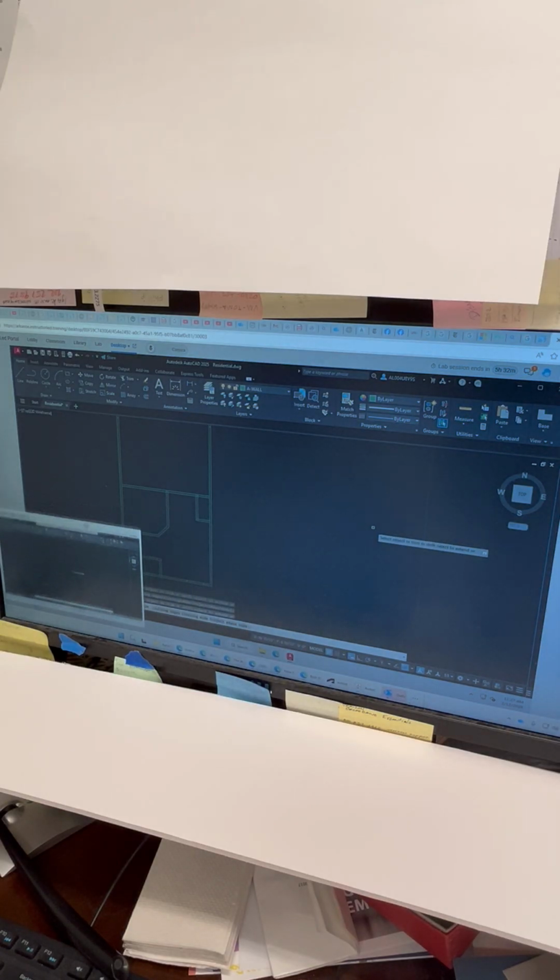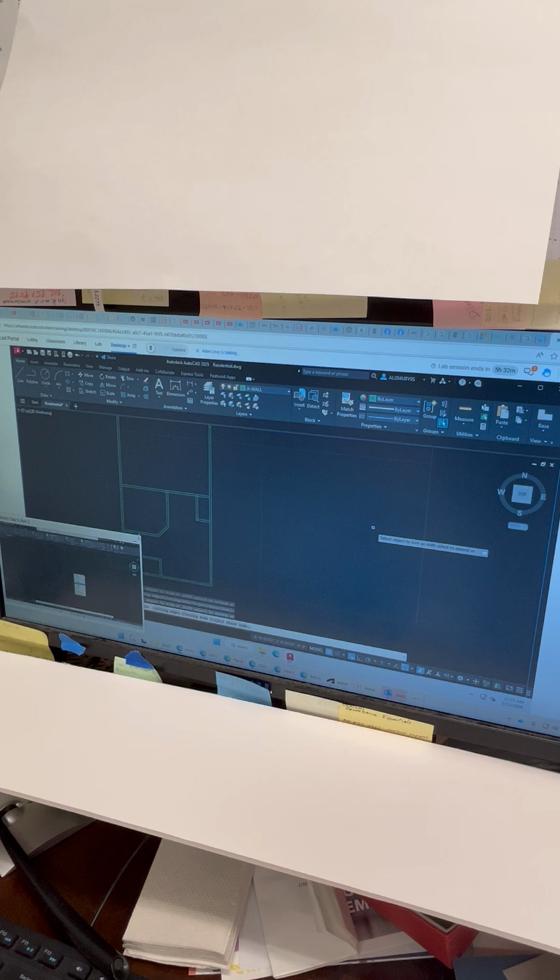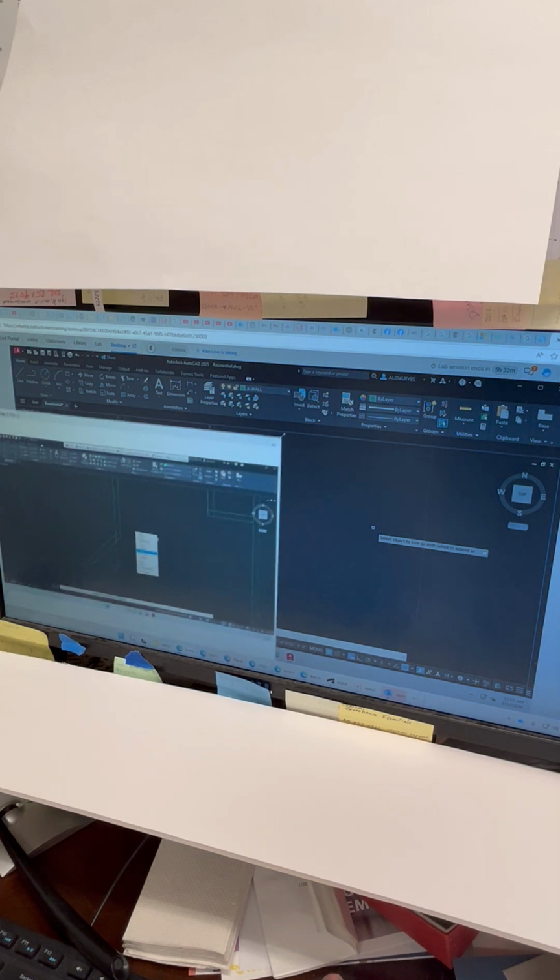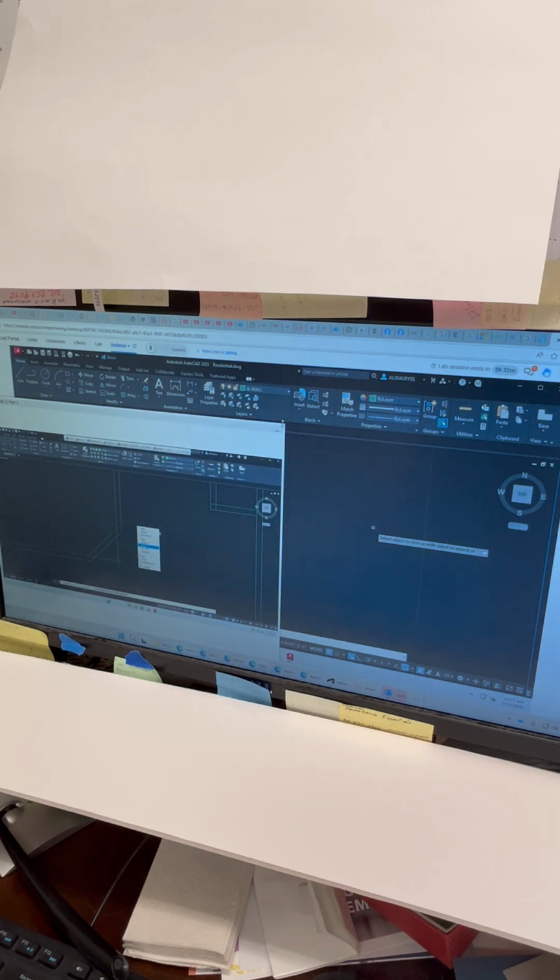And I want you to check the radius property, or option, I should say. We're going to make sure the radius option is 0. Generally, the default is always 0 in drawing. So you're going to go to R for radius, or here I right click to get to the options. It is 0.